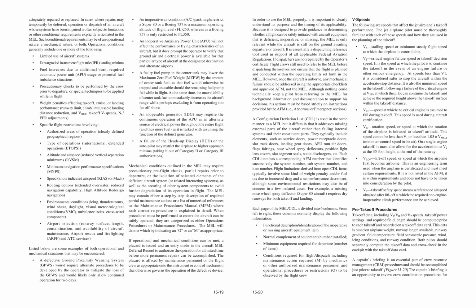Both pilots should separately compute the takeoff data and cross-check in the cockpit with the takeoff data card. A captain's briefing is an essential part of crew resource management (CRM) procedures and should be accomplished just prior to takeoff. Figure 15-20. The captain's briefing is an opportunity to review crew coordination procedures.